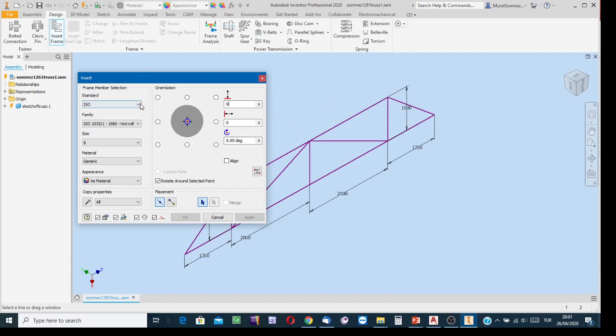Following stage. And then this part of the dialog box, well, obvious standard, select the standard. You're going to have the structural members as the ones designed and manufactured in accordance with the rules of which standardization association? That is the question. Drop the list and select the association. The abbreviation corresponds to that standardization association. Unless otherwise mentioned, use the ones manufactured in accordance with ISO.